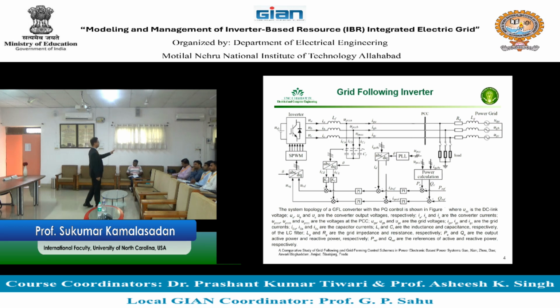One part is I need to first know whether the grid is there or not, so I can decide whether I should move with you or I should not move with you. That's the first part. Second part, if it is there, I have to get that theta, because I only get frequency, right? I don't get the theta. I have to get the theta, or the delta, out of that frequency. So there are two parts. Is that clear? The first part is whether I'm connected or not. The second part is I need to get it. Let's assume I'm connected. That means I need to get the theta or delta.